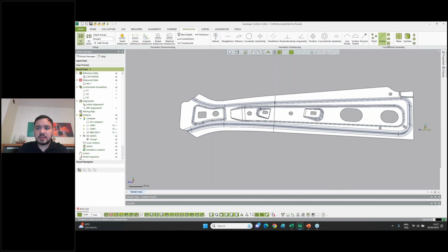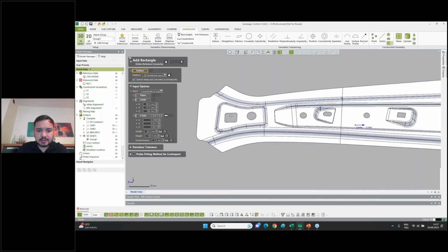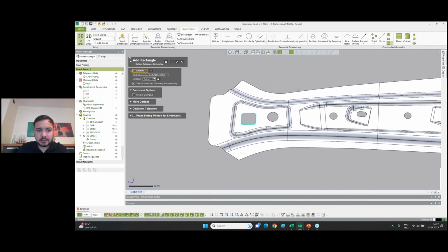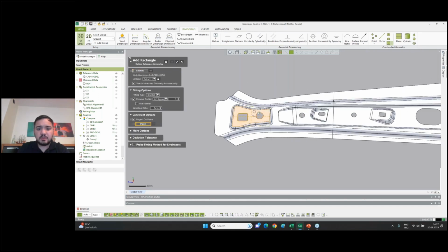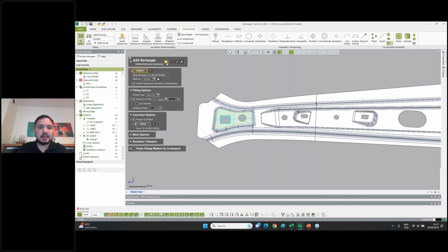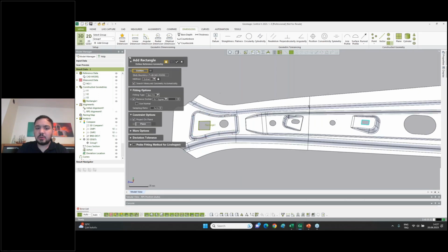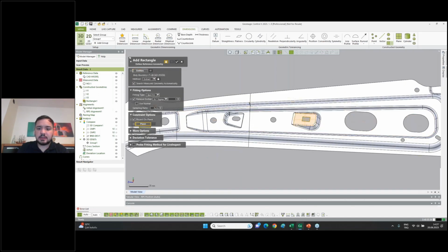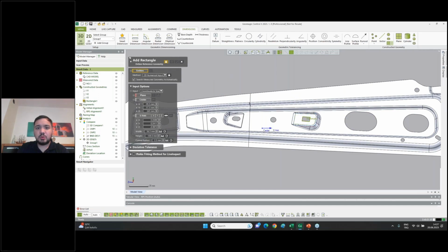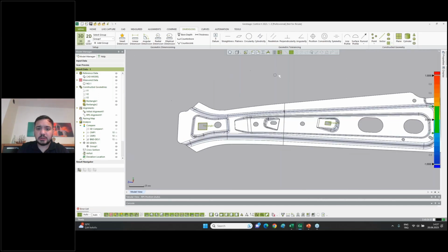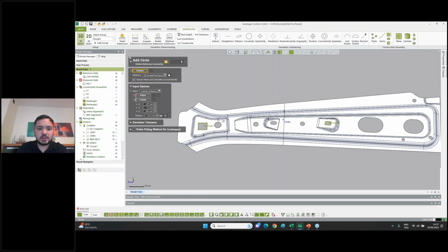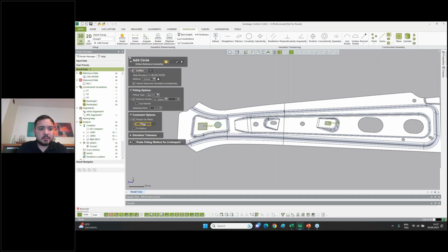You can do this using construct geometry like rectangle. I just select the rectangle spline and say project on plane, which plane you want. If this is the plane you want to use, just click it and then okay, you can easily do this. If you also create this construct geometry, you can easily inspect the position of the rectangles, and it is directional, not in GD&T only. We also see this feature after we use this method.